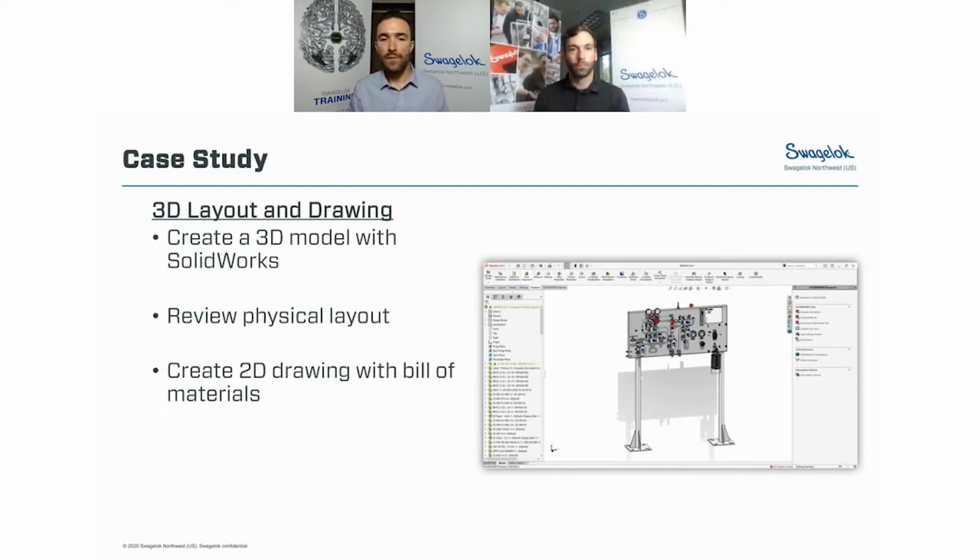So we went back and forth on what it needed to look like. So this panel, the standard design that I mentioned, would be about a third the size of what you're seeing here. So with the additional valving and eductor system, we had to increase the size of the panel. Then based on some physical limitations, we needed to shrink that down, add some extra supports here with the pipe stands in order to fit this system into its location of where it was going to go.